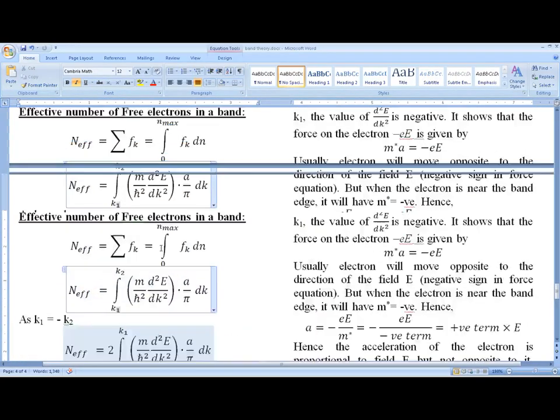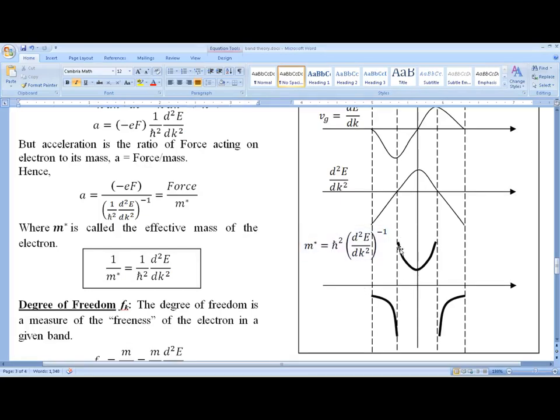We have seen the effective mass here sometimes becoming infinity, sometimes becoming positive, sometimes becoming negative infinity and negative. So in the first Brillouin zone, just if you consider from here to here, there the mass of the electron is positive. So mass of the electron becoming positive is quite convincing, but mass of the electron becoming infinity means electrons cannot exist at that particular point. So those electrons do not make any contribution to the electrical conduction. That's what we can consider. Now, mass of the electron becoming negative, this is quite surprising. How can we explain this?